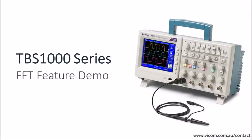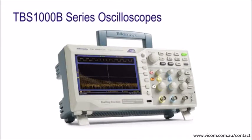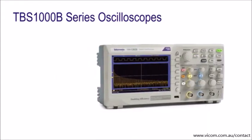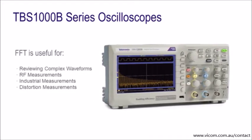The TBS1000B instruments offer a built-in FFT that can help you see the frequency content in your signals. The fast Fourier transform is an algorithm used to transform time domain information into frequency domain information. You can use the FFT operation on an oscilloscope to view and measure repeating complex waves as sine wave components.